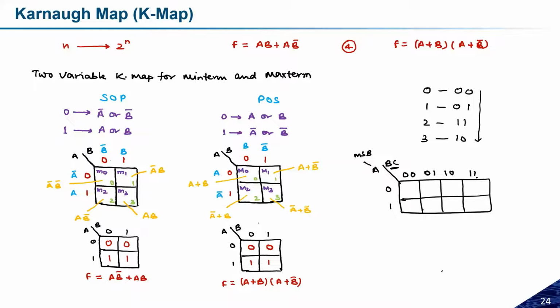But now, if you see here, initially I have 0, 0. Now I am moving to 0, 1, where I am changing a single bit, which is the second one. Now, if I'm changing from here to here, two bits are interchanging. So this is not possible. This numbering is not valid in the K map. So I have to use those numbers having only one change. So 1, 1 will be there, and the next change will be 1, 0.